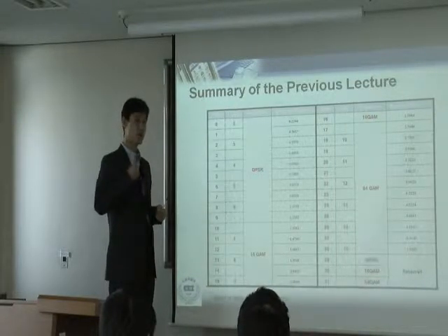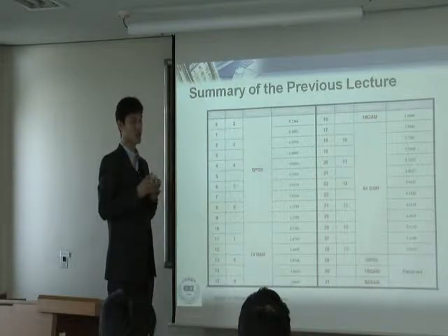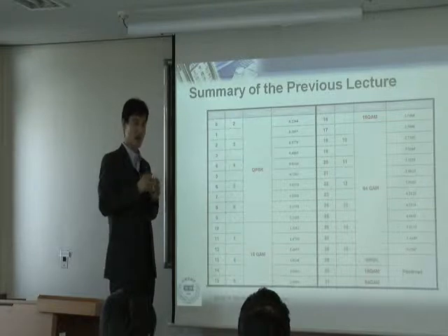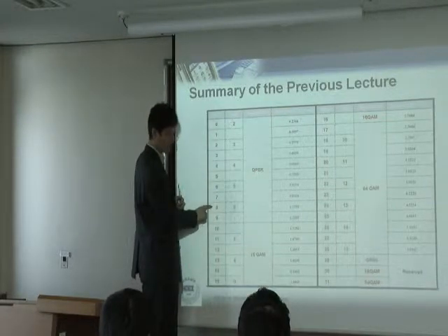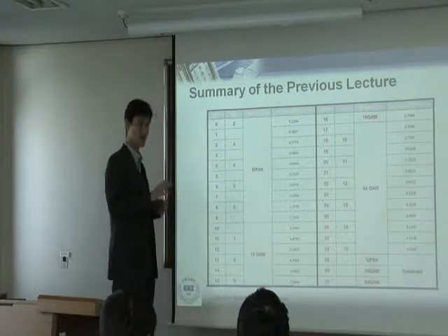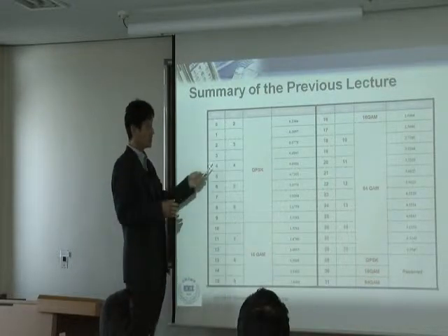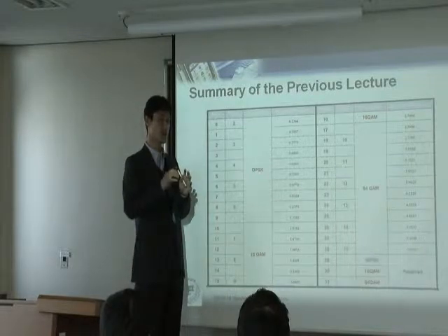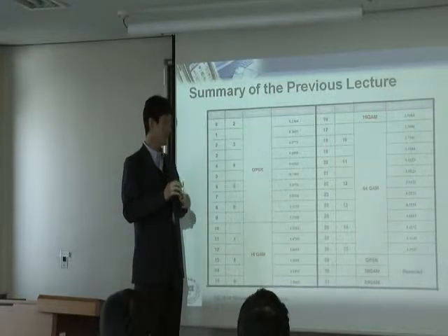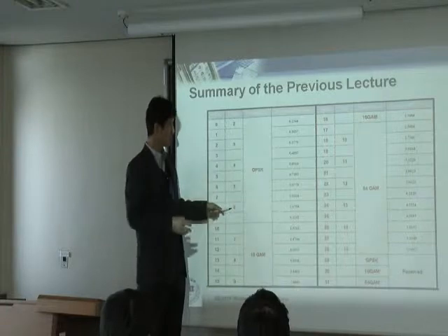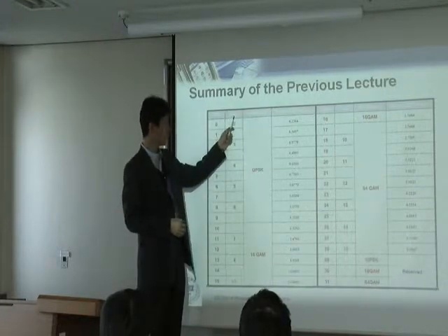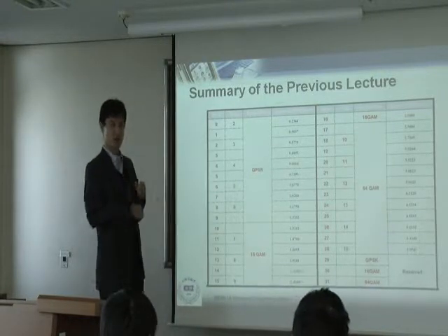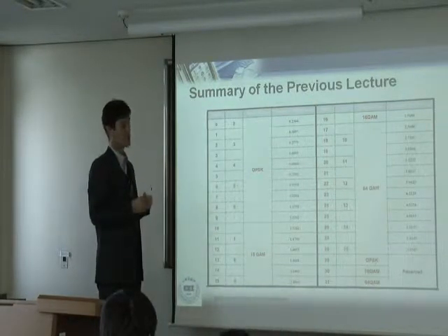So the receiver has to propose: my channel condition is like this, so based on my channel condition, I propose to use MCS 8. Something like that. Or the receiver says, my channel condition is this, so I'm telling you that my channel quality information is 6. Something like that. So the receiver will feed it back to the transmitter.